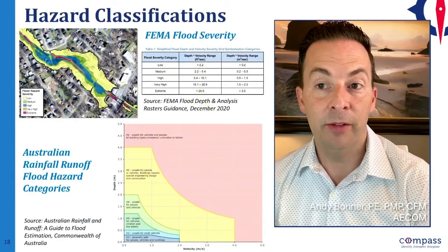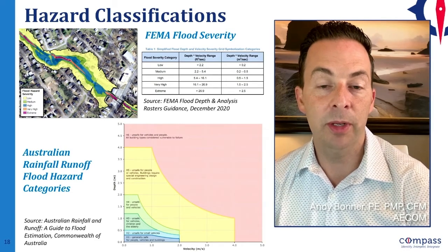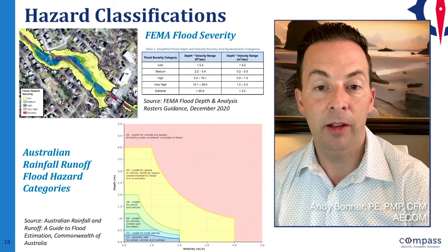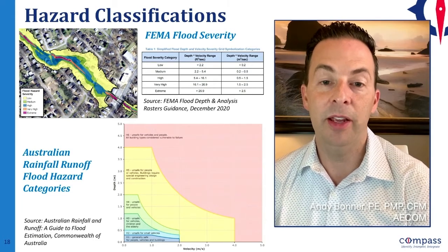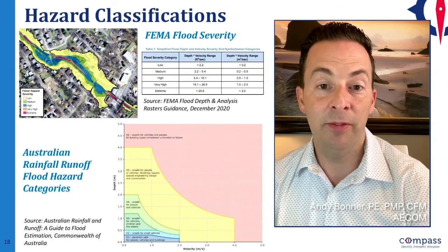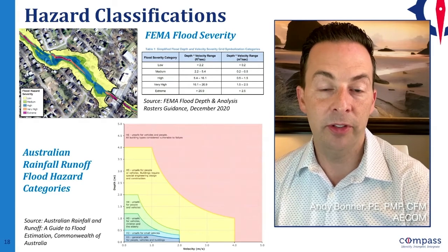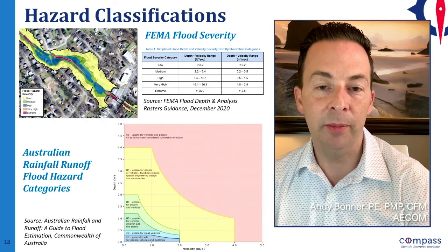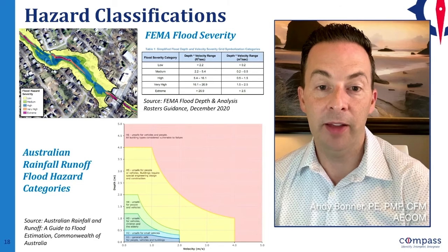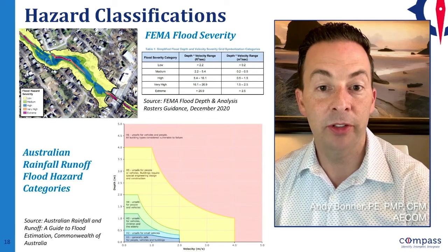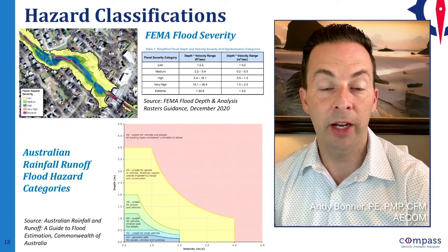So what we wanted to test, therefore, was if we took several 2D modeled streams that were available, delineated the floodways for them to meet surcharge requirements, and then compared those encroachments back to the underlying depth and velocity data of that 1% base floodplain to see if there would be any common linkages or trends. For example, if we went through all the different iterations and delineated the floodway for one of the streams at a depth times velocity value of 5, and that happened to be what it took to reach surcharge compliance for that location, did that apply to just that one stream, or would it apply to all the streams?